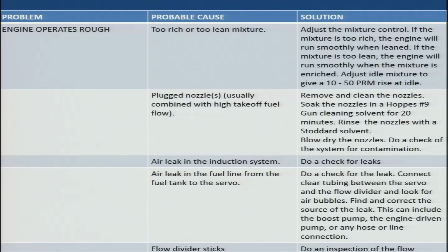Another problem, engine operates rough. Now, when you have rough engine operation, what might be the reason? Too rich or too lean mixture. When the mixture is either too rich or too lean, you will have rough engine operation. Another reason might be that the nozzles are plugged, nozzles are blocked. Another reason, air leak in the induction system, leakage in the induction system.